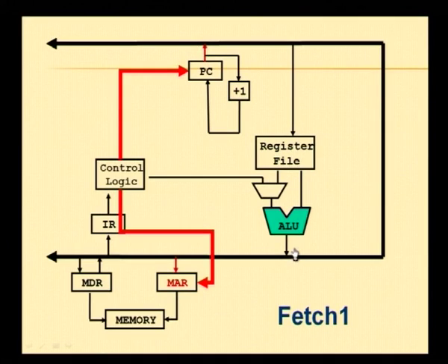Now this storing of the result, you may either have to store it into memory or you may have to store it in the register file. If it is stored to the register file, then depending on the instruction, the output will be stored back into the register file, or if it has to be stored into memory, the output of the ALU will be given to the memory data register, an address will be specified, and you will actually do the memory operation here.